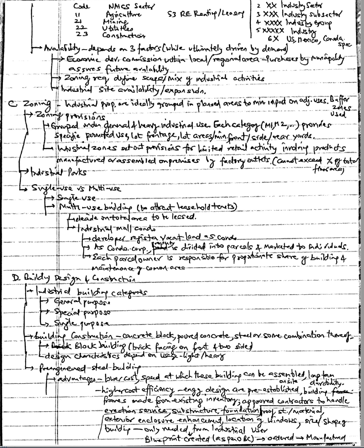To recap, there are five kinds of sprinklers: wet pipe, dry pipe, pre-action, deluge, and combined dry pipe and pre-action. Nearly all automatic sprinkler alarm systems will include a trigger followed by a flow of water that sets off a water and electric alarm. Both systems can be connected to a local fire alarm.